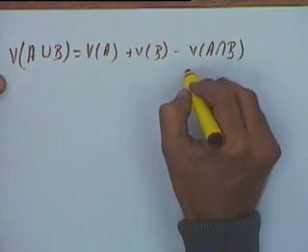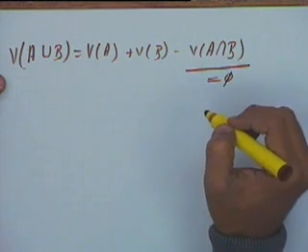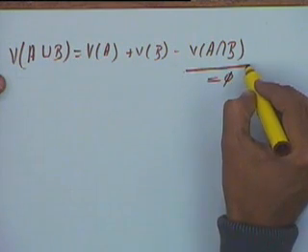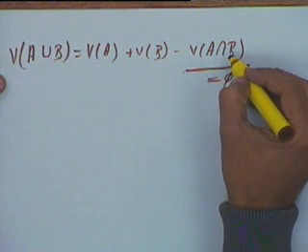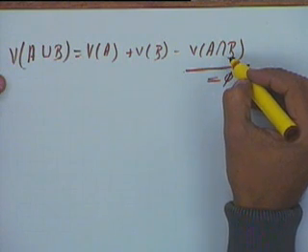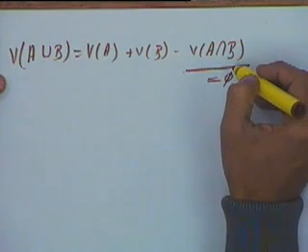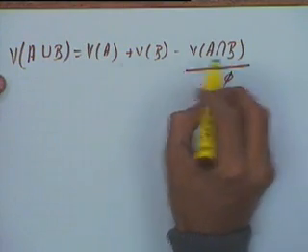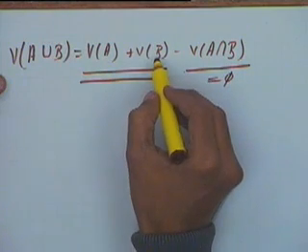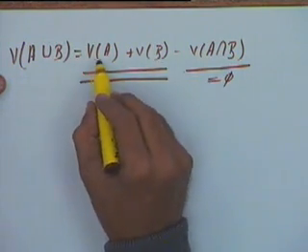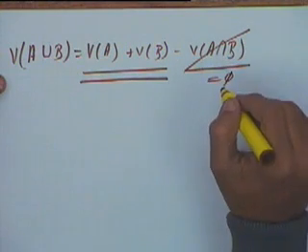In this case, if I can ensure that A intersection B is equal to 0, that is equal to a null set, then the volume of A intersection B will always be 0. So there are modeling techniques which ensure that A intersection B will always be 0. The intersection of all solids will always be 0 in that case. We will see some of those modeling techniques. So in that case we can easily use this method of finding out the volumes, because A and B will be primitives or will be derived from primitives. So the volume of the objects can be easily computed. And we know that the intersection will always be 0, so we will always ignore this term.